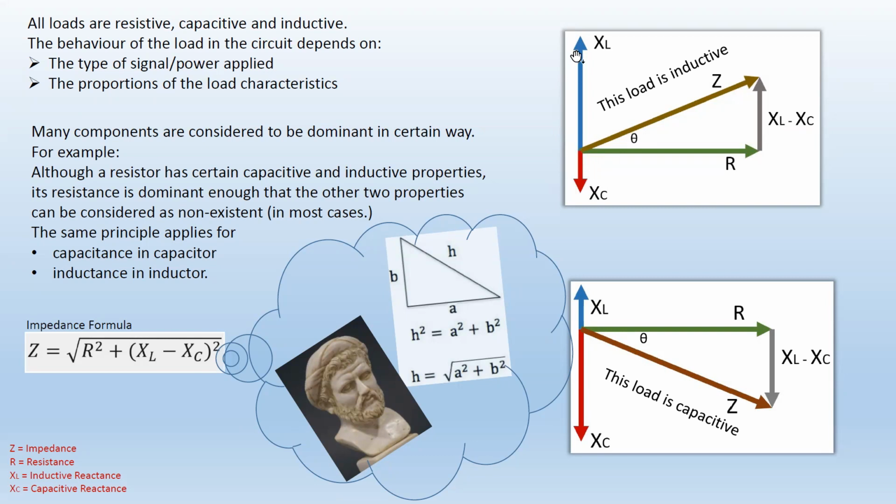Okay. So the total reactance, we just sum these up. And because in this case, the inductive reactance is greater, we're going to have the vector pointing up, because you take this here, apply it to here, that's going to become that much shorter. All right, so we apply that total reactance, and you have the total resistance of the circuit. And if you draw a line from the 0 point right to this point, that's the impedance that we designated with the letter Z, or Z if you're from the States.